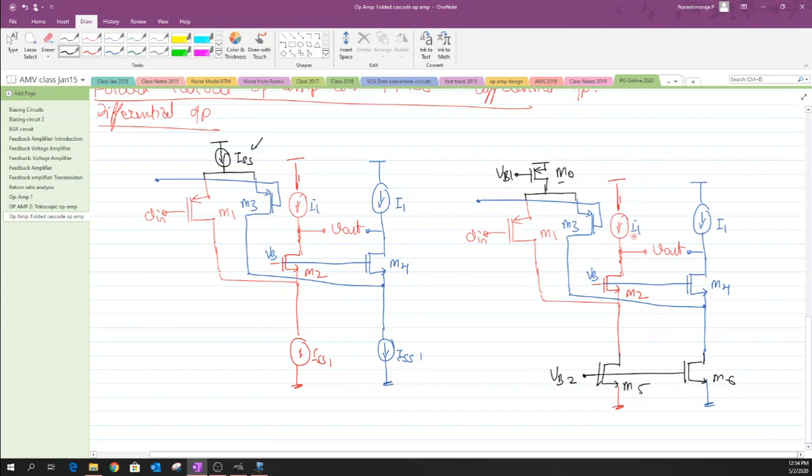The type of amplifier that is used to realize this I1 and I2 is supposed to ensure that they have the same similar impedance that they see when we look down across this Vout node, right. So which means that one cannot use a single transistor to realize these I1 current sources, but rather one has to have a cascode structure in order to realize these current sources of I1s. Okay, so let me replace these I1s with a set of PMOS transistors that have been stacked such that they create what is known as